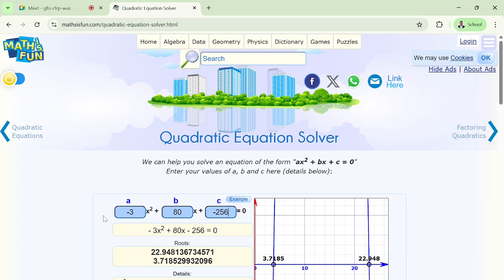In the last problem it was not the case, because there it was not an absolute maximum; we had a monotonous function. But here it goes and changes the curvature sign. We have a decreasing and then increasing function. So wherever my bending moment attains a maximum value, the shear force changes sign. This is an important property that we need to know.